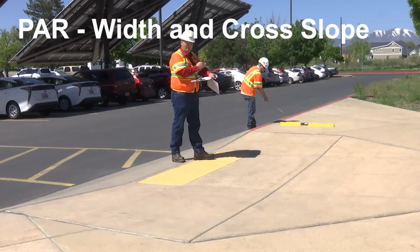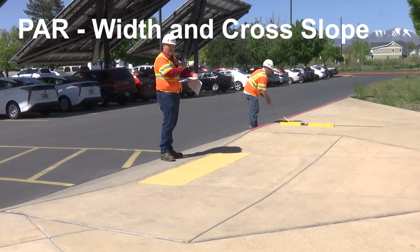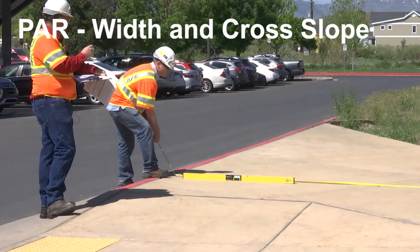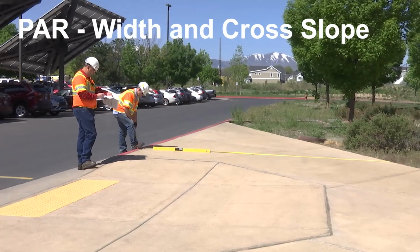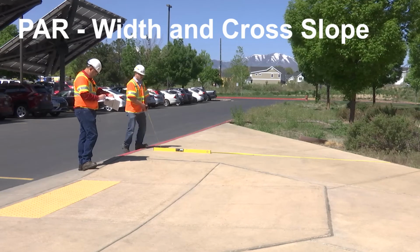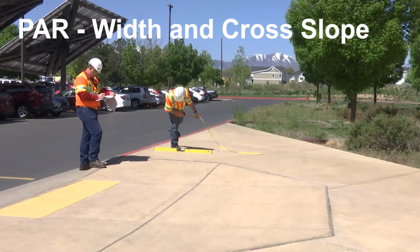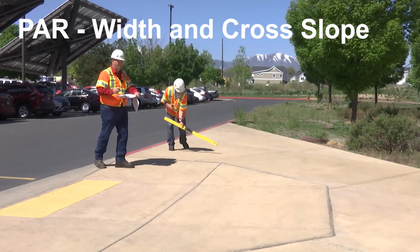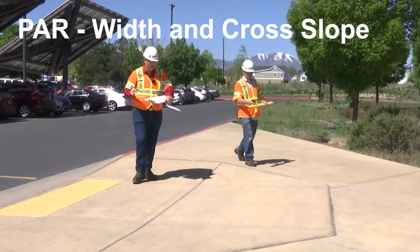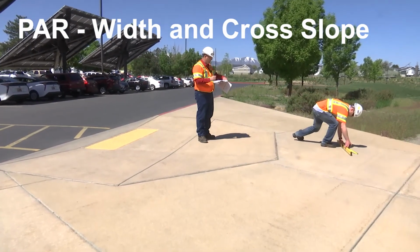So first, for the width off to the left, we can see that we have quite a bit of width here, 16 feet, and a cross slope of 1.2%. So we meet the requirements there. Next, we will take these measurements at the location in front of us.